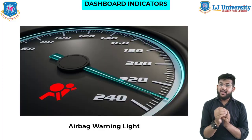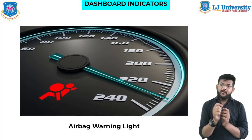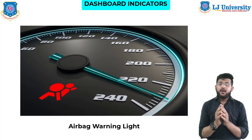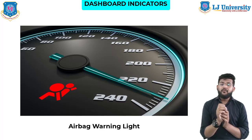Next is the airbag warning light. What is the meaning of the airbag warning light? The airbag light is on when there is a problem with the airbag system of the car. The airbag indicator light could turn on for many reasons. If the airbag was previously deployed and hasn't been reset properly, the light will come on as the airbag cannot be activated. If you haven't deployed the airbag and the light is still on, there must be a problem with the ECU system of your vehicle.